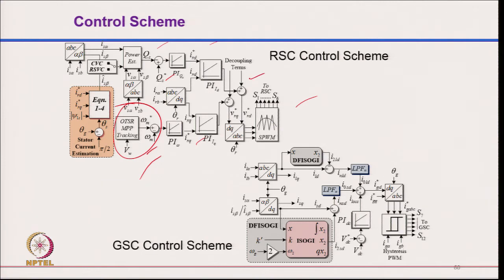And then you have a voltage control. Normally we use 1.8 kilohertz switching frequency for the rotor side converter. So, we normally have voltage control after getting this. The vector control quantity of rotor voltage is converted from the slip angle into 3 phase, and then we have the rotor side converter control, and this is the grid side converter control.